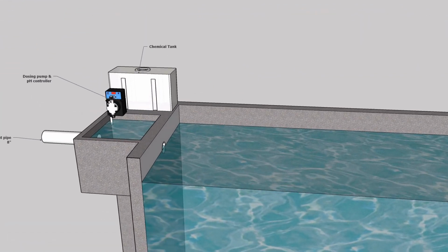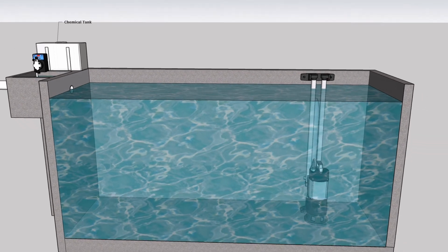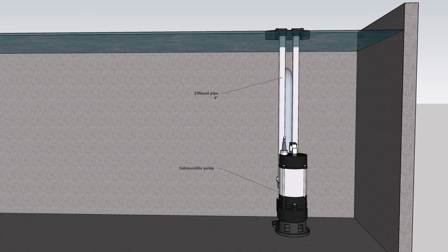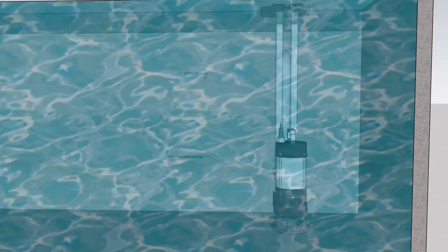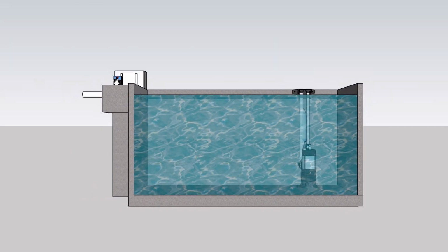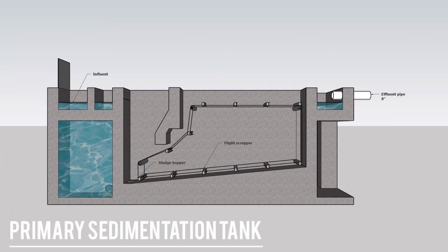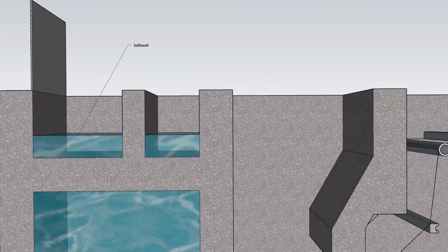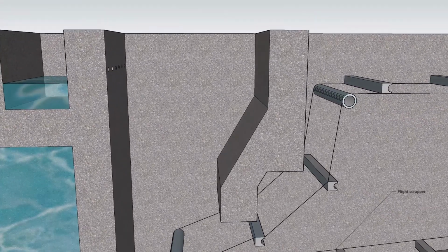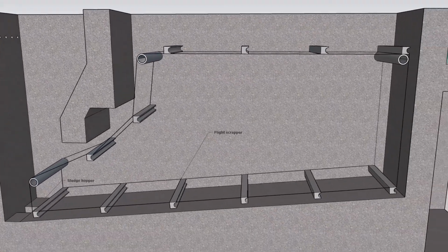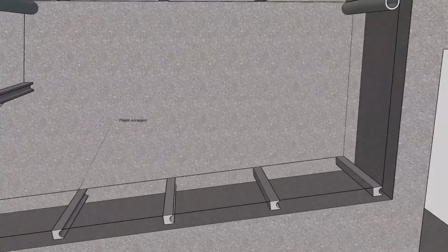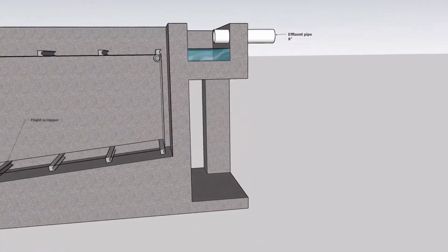Next, the equalization tank, which is a unit that stabilizes the water flow and its temperature before being pumped to the water treatment unit. Starting from the influent box, the wastewater is stored inside the 4-meter depth tank, collected and pumped through the effluent pipe with uniform flows. The wastewater will then enter the sedimentation tank. As the name suggests, a sedimentation tank functions to form sediment by allowing solids to settle by gravity to the bottom of the tank, which is then routinely swept by a flight scraper into the sludge hopper or an effluent hole for the sludge.